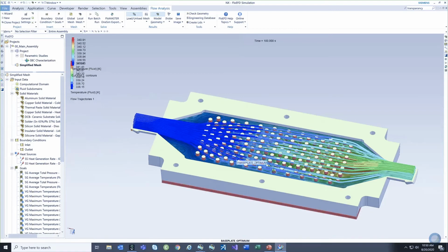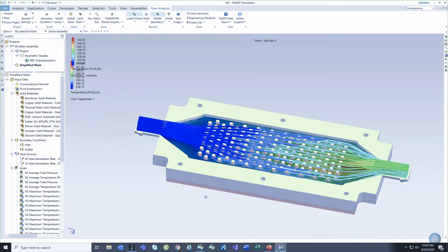we start to interpolate in what we call engineering methods, right? So we know what flow past a flat plate looks like in terms of the behavior of the boundary layer. We know what flow over a cylinder looks like. And we basically take those textbook behaviors and bake them into the solver so that when our mesh becomes so bad we can't solve full Navier-Stokes in an accurate way, we pull in these engineering methods.